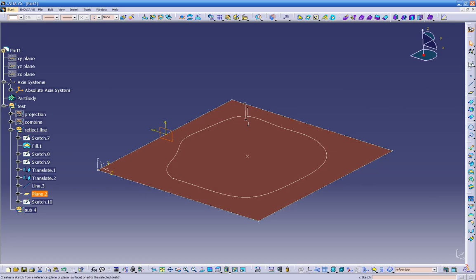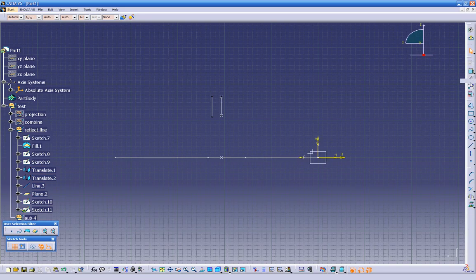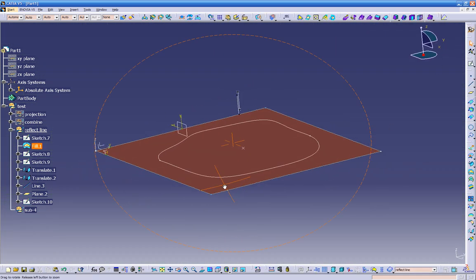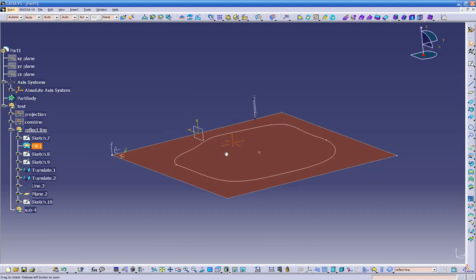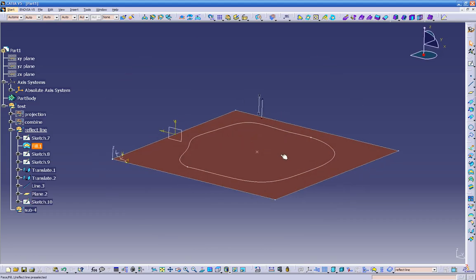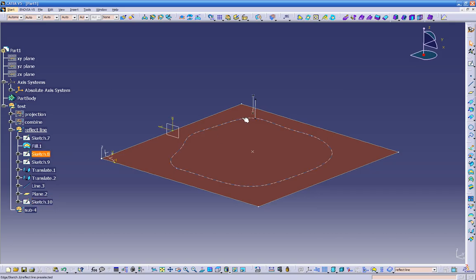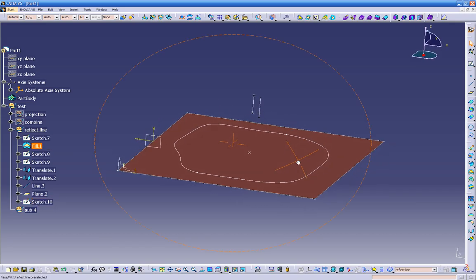The moment you open a sketcher, you can tell how many options you have to create your geometry. But we don't have that many options and icons to create our geometry in a 3D view. So it's always better to use the sketcher to create your stuff. But when I do quick and dirty constructions, sometimes I use the 3D constructions. You'll get used to it. When it comes to it, you'll choose whatever is easier.